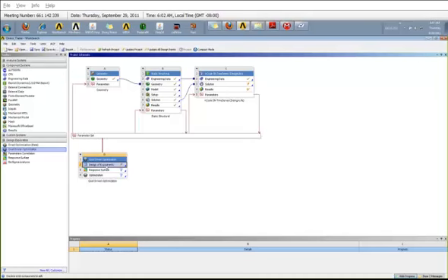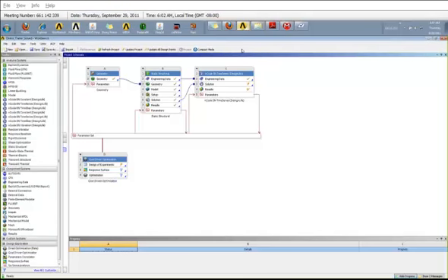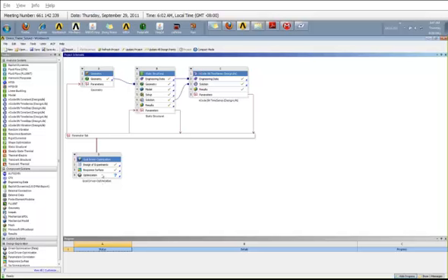So now I can go in, do the design of experiments, create the DOE matrix, solve it, then do a response surface, then specify the goal for the optimization and select the best candidates from the response surface. To save some time, I have already solved a design of experiments and response surface. The only thing I have not solved is optimization, which I will show you in a minute.